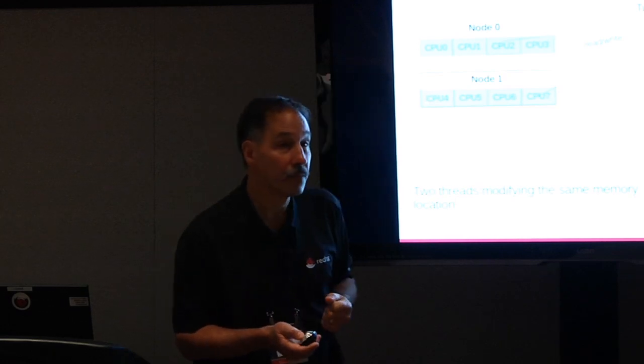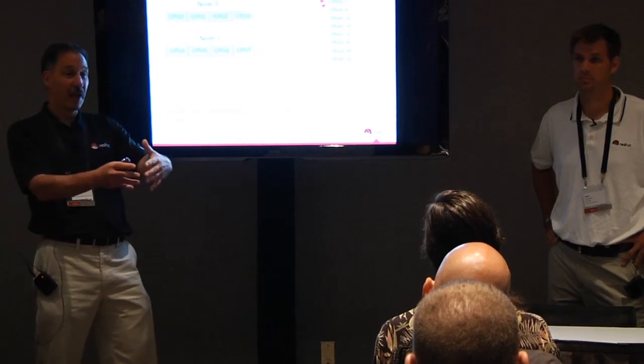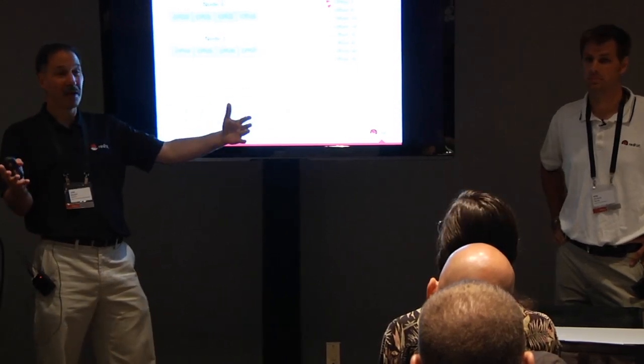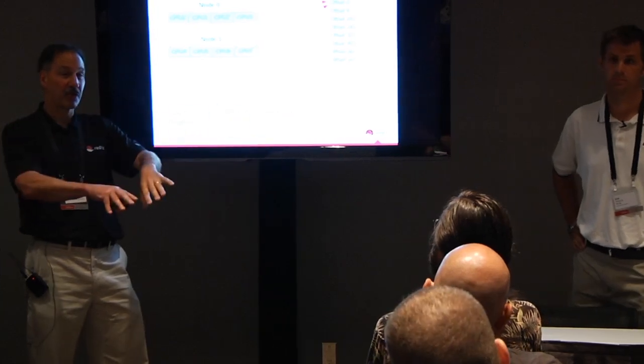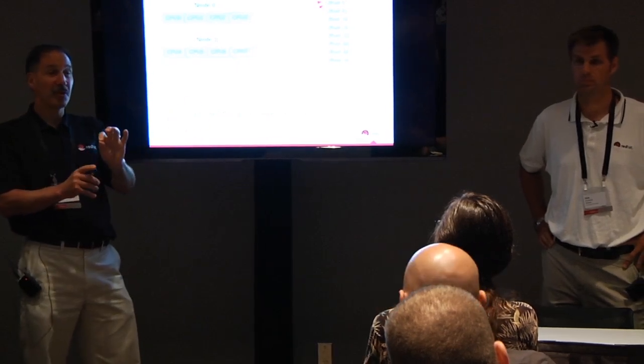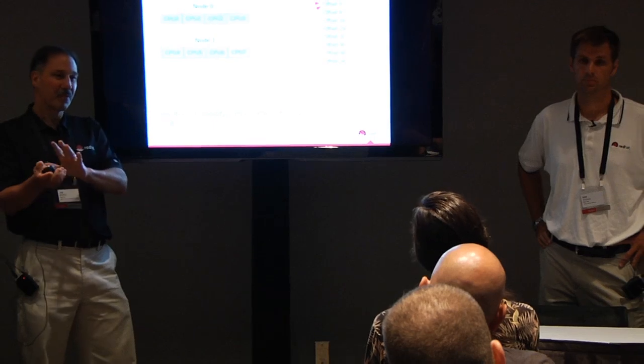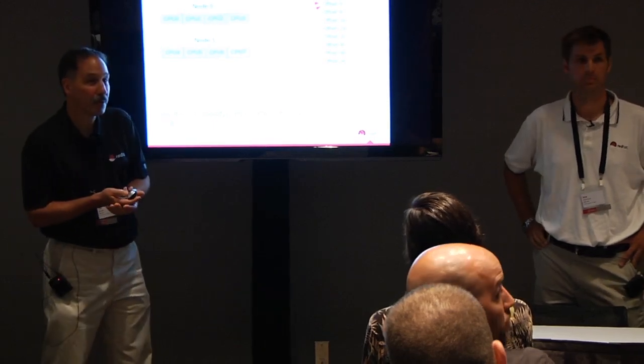What happens when processes contend for the same cache line? It means you're exhausting the cache line because it's a four-way set associative cache, and you're exhausting all four. We are not getting into the associativity. Let's say you have an 8-way associative cache, then you have 8 addresses that could collide; once you go beyond 8 addresses that map to the same set, you start to collide. It's not something you can control that easily, and that's not part of our talk. You can only know you have it.